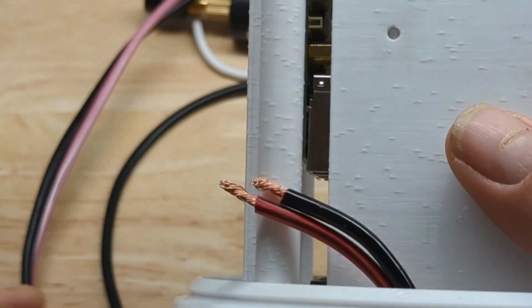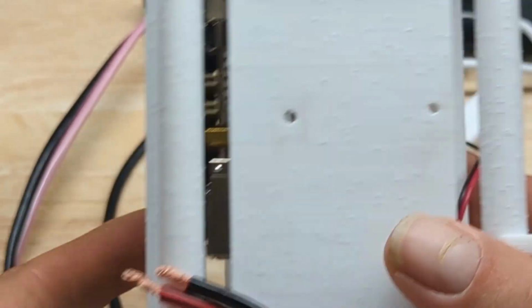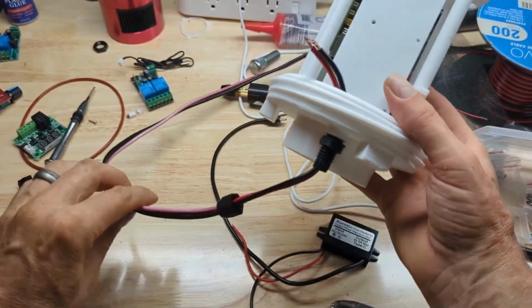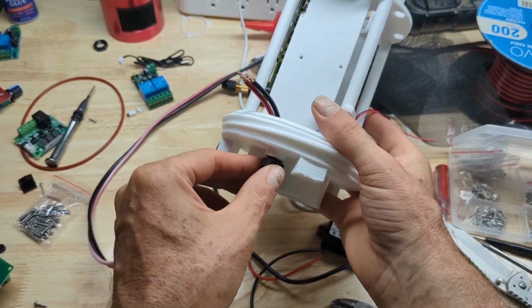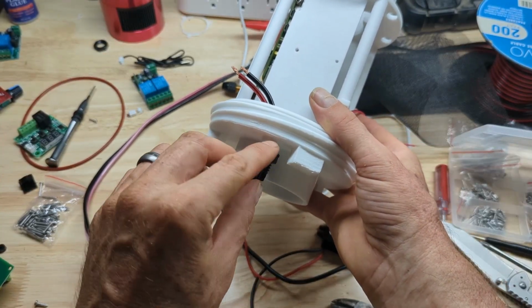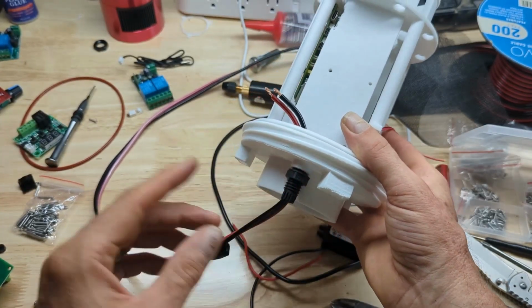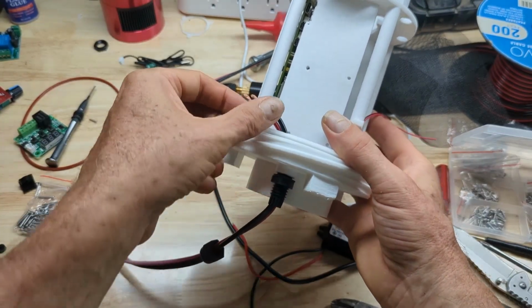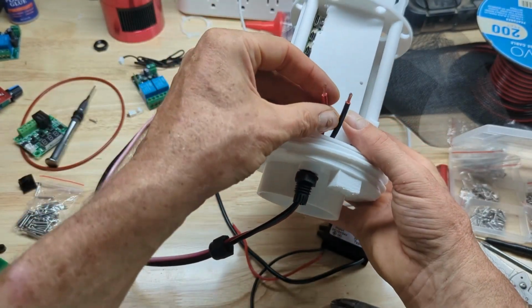Okay, so next what we're going to focus on is getting our power block installed. So I've already pulled the power wire in. It's got a little 12 millimeter cable gland. Remember, it threads up into this port. It's already pre-threaded. That's where you'll use your 12 millimeter bolt to clean the threads and make sure everything's good. And we'll have these just extending up into here.